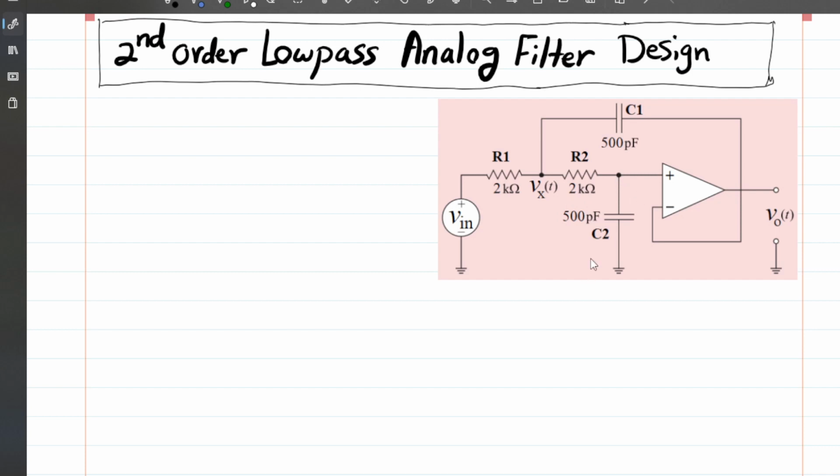When we say this is open, C1 is open as well. And because this is an op-amp in complete buffer mode with negative feedback enabled, whatever voltage appears here, in this ideal op-amp scenario, appears at the output as well. So in super low frequencies, close to DC, you can assume Vin appears at the output directly. Basically, the gain of the system, Vout over Vin, is 1.